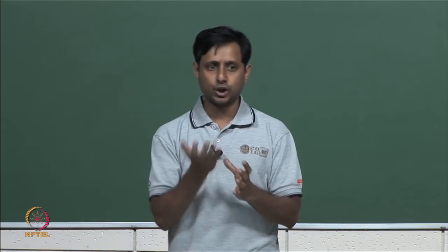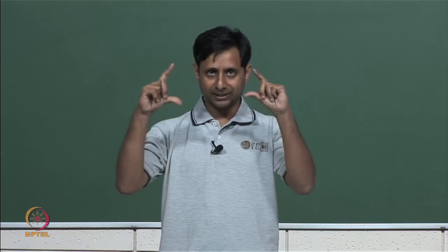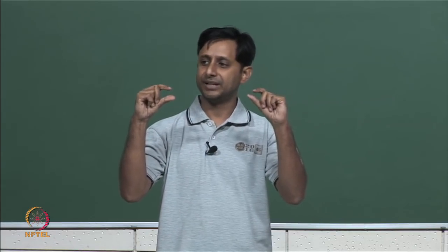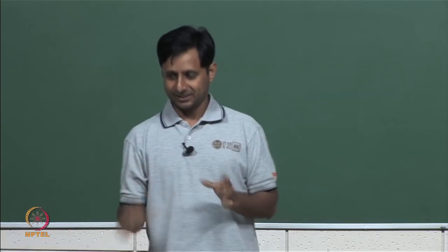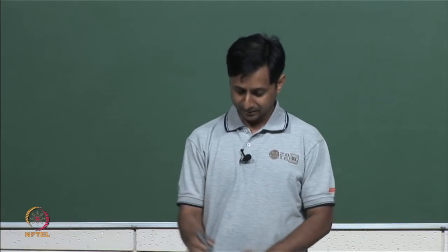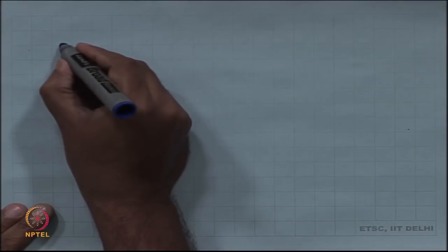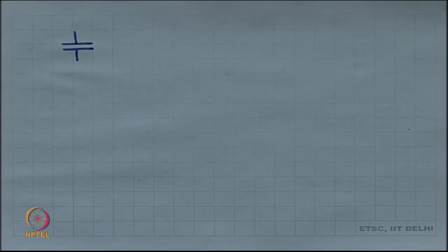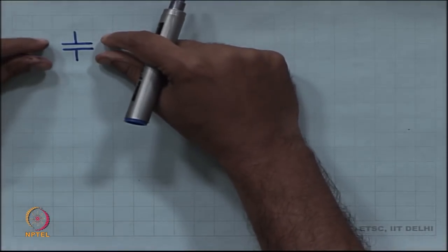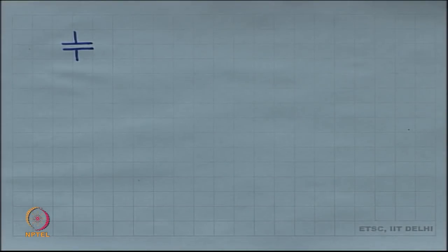You want to control the charge in the channel, you have to make the thickness of the gate very small, and this is where the disaster happens, right. The MOSFET is like a capacitor, right. You are making the thickness of this dielectric thinner and thinner and thinner, right.